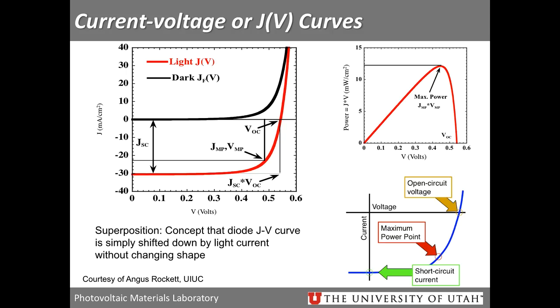Okay, so how do we characterize PV? The first, as I mentioned, these are diodes. So the most basic characterization is looking at the current voltage characteristics of a solar cell. In the left-hand corner, we have kind of an ideal diode curve of a solar cell. The dark would be a solar cell in the dark. If you shine light on it, you get a shift in current. You start generating current, and so your IV curve just shifts down.